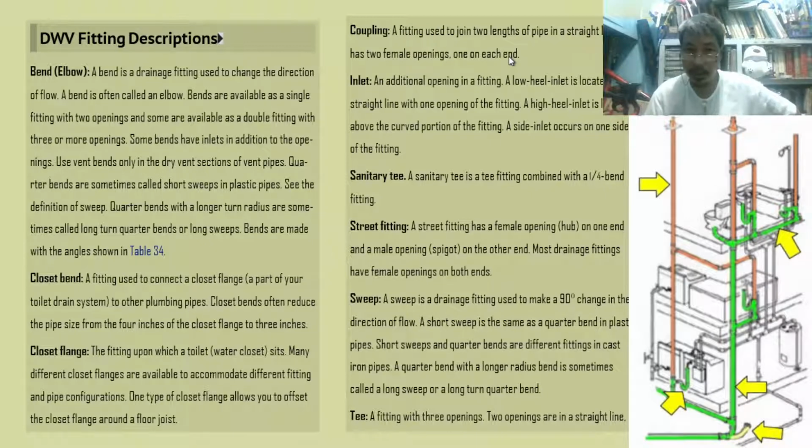Coupling is female. Inlet, an additional opening in a fitting. A low heel inlet is located in a straight line with 1 opening of the fitting. A high heel inlet is located above the curved portion of the fitting. A side inlet occurs on one side of the fitting.